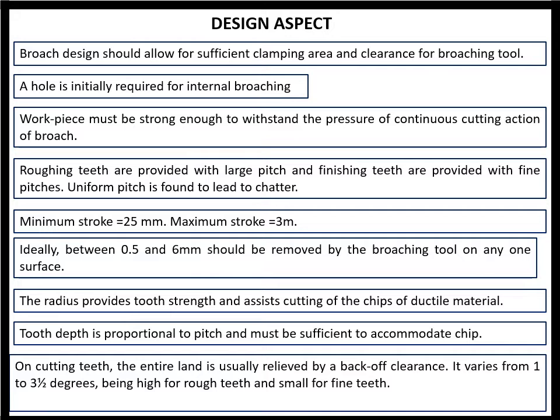And for all the roughing teeth, one should remember they should be provided a large pitch, whereas the finishing teeth can have fine pitches. But if the pitches are kept constant or uniform throughout the roughing and finishing teeth, then there is a possibility for chattering.